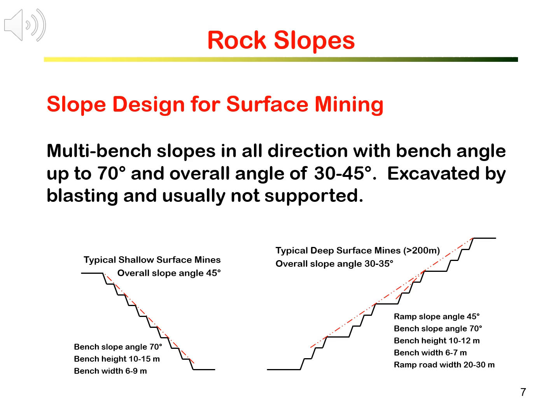The overall slope around the mine usually has an inclination angle of 30 to 45 degrees. Those angles depend on the depth of the mines, as well as the slope rock mass quality. Typically, shallow open pits can have a slightly higher overall slope angle, while deep open pits will have a lower overall slope angle. Slope angle also reduces with decreasing rock mass quality.